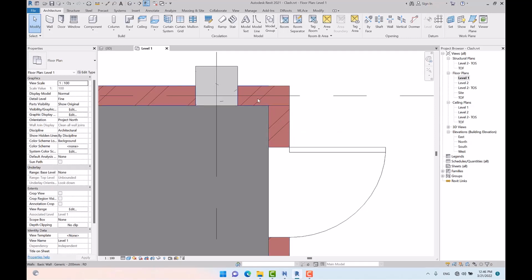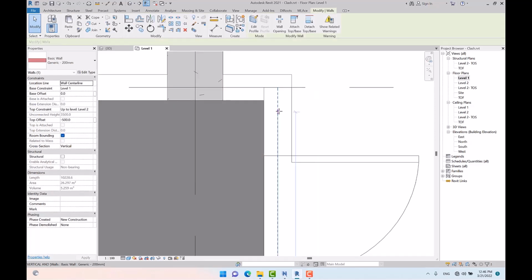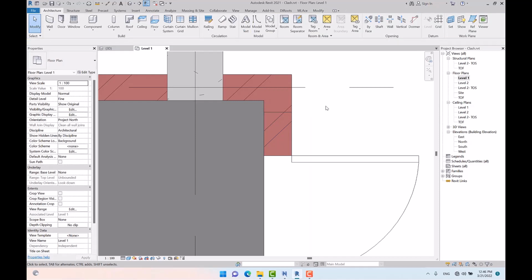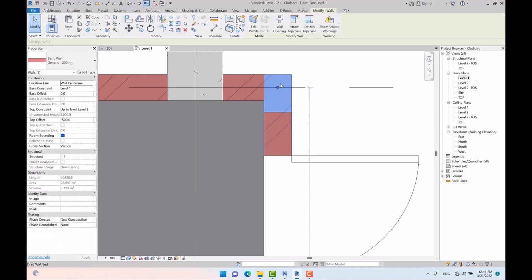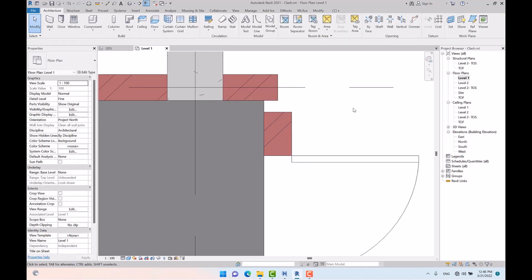But right now, to convey the message better, I want to show the connection between these 2 walls. I extend the wall downward. As you can see, the other one is extended to the end, but the second one is not extended, so this clash is not recognized as a duplication. So I consider this a weak point of Navis. Anyway, to make it more comprehensible, I trim these 2 walls this way, as you can see. I disconnect them from the other walls this way.